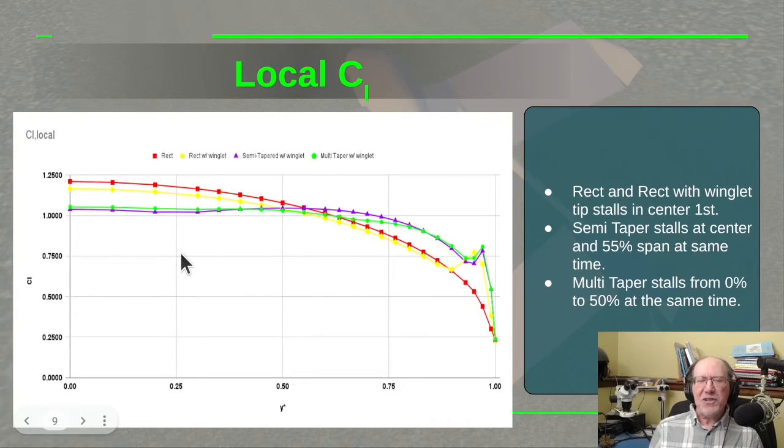But you can see how this is different than the shapes we had before. You can see there's an interesting little spike out here. So this is not lift distribution, this is coefficient of lift distribution. But it's going to behave a lot like the lift distribution, where we multiply by angle of attack, and this will increase or decrease as we change that angle of attack.